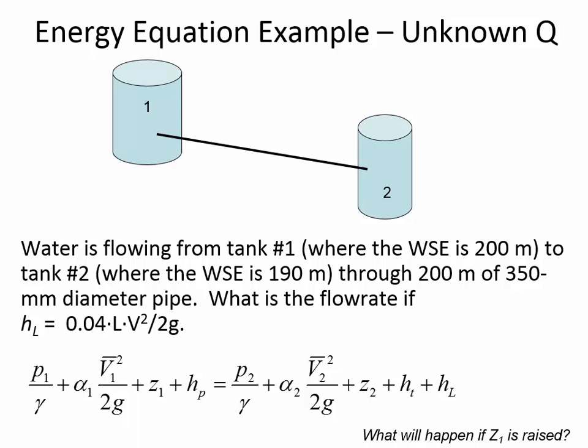And when you get into hydraulic engineering, when you take water resources, 341. Are you registered for 341 in the fall? Tomorrow. Okay. What you'll find out, h sub f, the formula that we usually use for hydraulic design, is f L V squared divided by D 2g. And so D does affect the head loss. Now here, they've combined the friction factor and the diameter into one expression. That 0.04 accounts for both. But more generally, the diameter does have an effect on not only the velocity, because if you have a big diameter, that's going to bring the velocity lower, but it also has a direct effect.